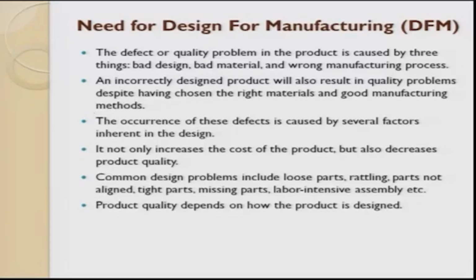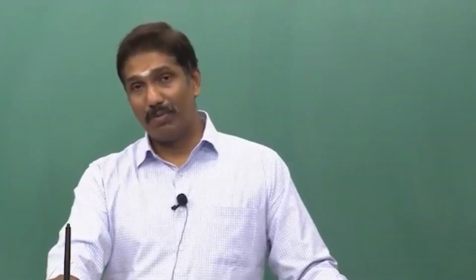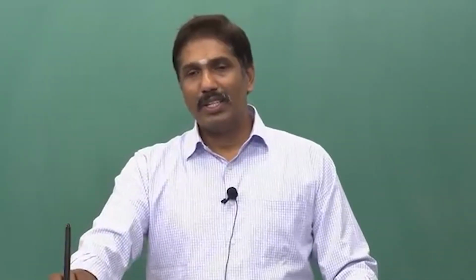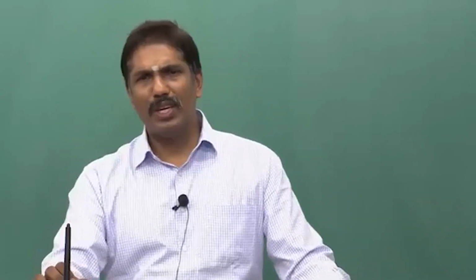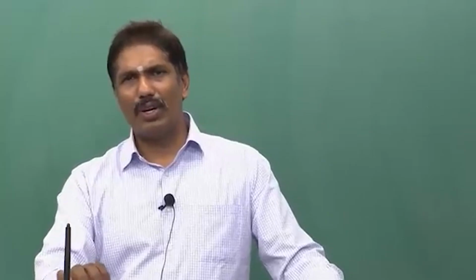So, here you are choosing a manufacturing process, and when you choose a wrong manufacturing process, what happens? In extrusion, the load is uniformly distributed. That means the grain size and the defects are all taken care of, and the output you get is of very high quality in terms of strength.